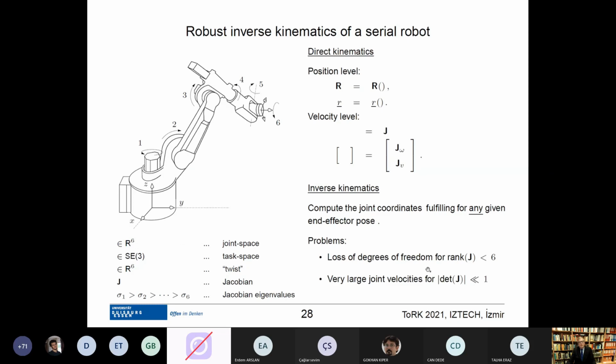So here something happened with the typos, but we are not going to go into detail. So here we have a 6-axis robot, and in a singularity, more or less, you can imagine that 2 axes operate on the same target space, and then you lose, of course, 1 degree of freedom in the complete space. So more or less, this is what happens in a singularity. So you still have 6 axes that you can still control, but 2 are operating on the same subspace.